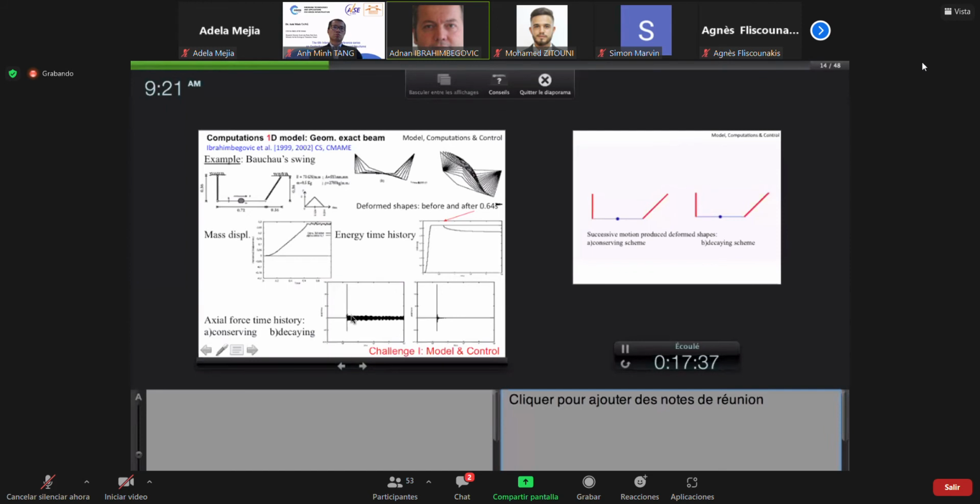basically stresses which are completely useless, because typically here we had only 8 elements. You cannot really cover all this. You cannot represent the high frequencies correctly. So the only thing you can do is remove them. So the so-called energy decaying scheme, I'm going to comment on how you actually do that.